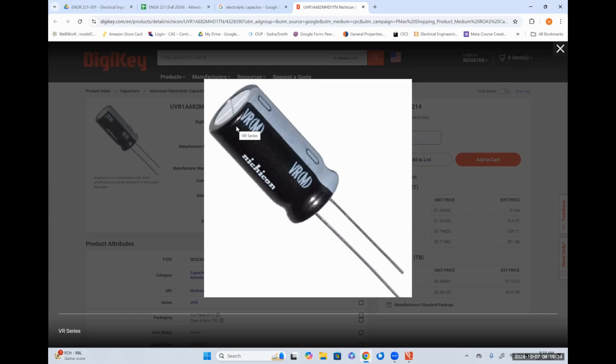So this is a really good indicator of, hey, there's something wrong with my power supply if I ever see one of these burst, because somehow a negative voltage made its way through. So that's an indicator that the rectifier has failed. Okay. So that's why they're used.